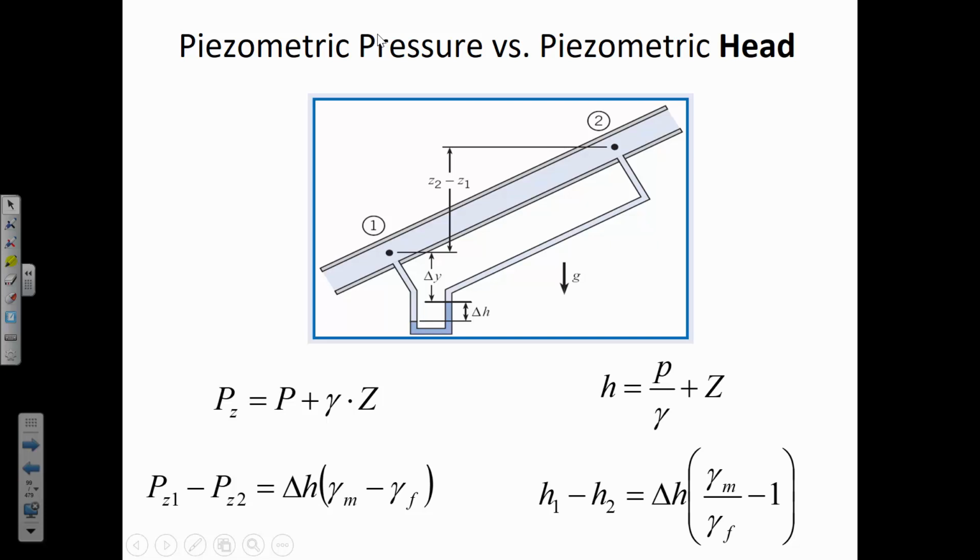Let me blank this up because I'd rather have your attention on the whiteboard for just 1 second. Remember when we were talking about a piezometer? We've got this pipe with the alternate conduit sticking up out of it, and the water level rises to a certain elevation. Okay, so this was the piezometer. That's what this device is. So this device is a direct reflection of how much pressure is in the pipe.